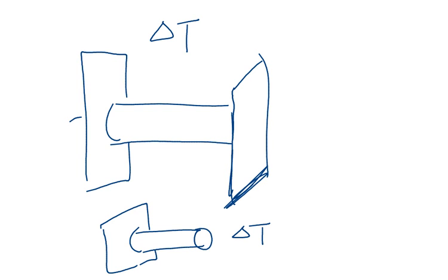So how do you consolidate these two different situations? Well, it's actually quite simple, okay? All you need to do is look at a temperature change as another way of loading your part. Okay, so if you look at delta T as having the same effect as applying a force, now it makes sense, right?